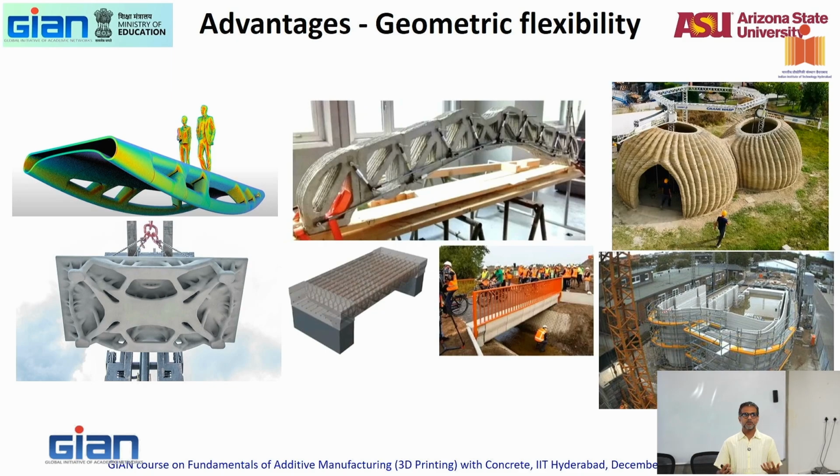There are a bunch of earthen structures that are coming up, building with clay and very little concrete to simulate ways in which people lived in the olden days. But if you look at this, that's a completely compression controlled structure. No tension at all anywhere, which means no reinforcement, right? No reinforcement, one half of the problem solved. But again, to print it in a way with overhangs and with geometry that is curving so much, you have to have material that is set on demand and things like that. A little more complicated.